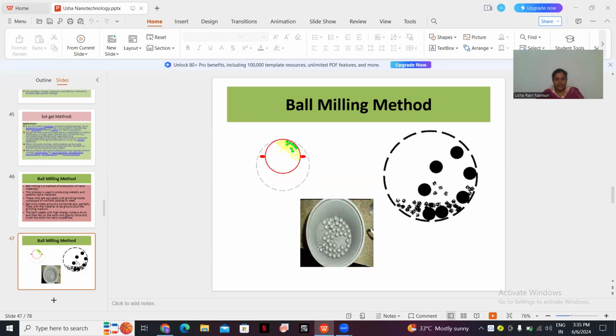Magnetic and catalytic nanoparticles are usually produced by this method. Here a container is packed with stainless steel balls a few millimeters in diameter. The material to be crushed is added as a powder of about 50 micrometers grain size. A rotating shaft crushes the material in liquid nitrogen in the container. The grinding period ranges from minutes to some 100 hours.